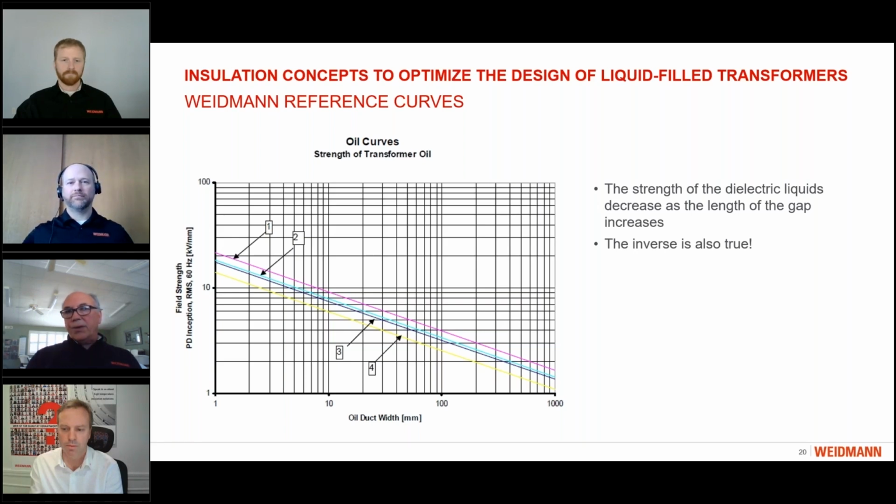And as this question mentioned, there are tests done in air and also tests done in oil. In most cases, the results are very tightly related to the electrodes themselves. So what you measure in a test according to a standard isn't exactly what you would apply when designing the transformer. But to finally come back to the original question, you should not use strength in air for designing a power transformer.